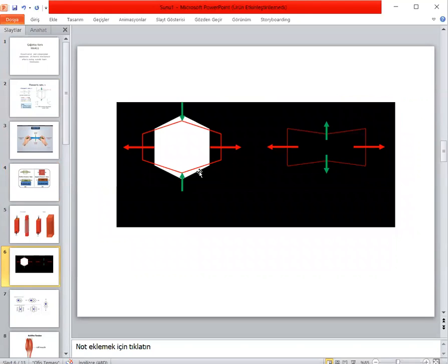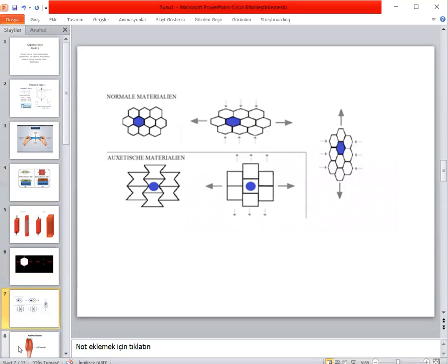In this picture, I'm going to say something about structure. This is a convex structure, you can see, and this is a concave structure. In the structure of the materials, if there is convex bonding between the molecules or atoms or some subparticles, our materials are more prone to having a positive Poisson's ratio, I mean conventional materials. If the bonding or interactions between atoms or molecules are concave, this makes our material auxetic. You can see it here also.